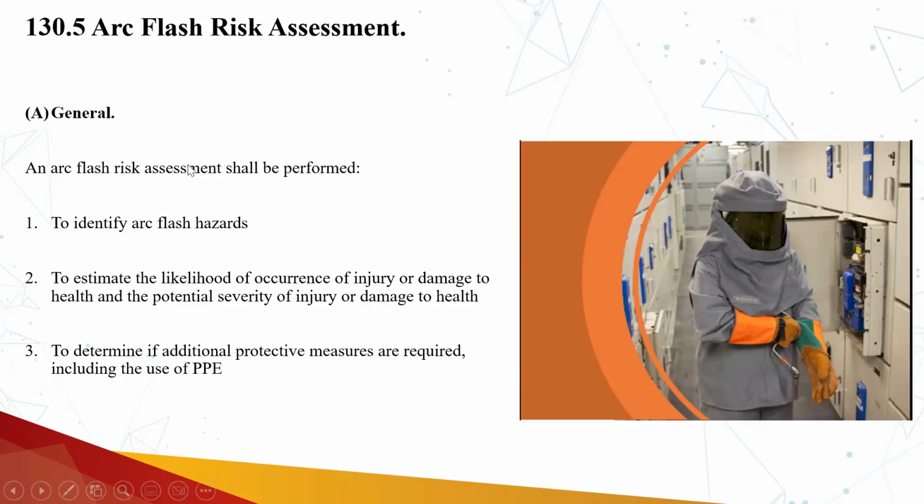Yes, Sanjay, please. Sir, this is totally, I guess, irrelevant, but I want to ask this. Yeah, sure. Arc blast energy, sir, how much is it? Basically, arc blast is not in terms of energy, it is in terms of pressure. It's pounds per foot square. Arc flash is energy. Arc blast is not energy. If you look in the first lecture, we discussed the arc blast. It's basically the pressure wave component.